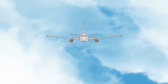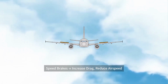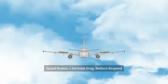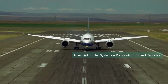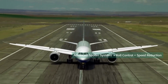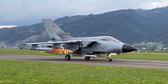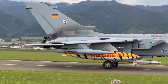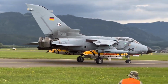When used as speed brakes, spoiler panels on both wings extend upward simultaneously, increasing drag and reducing lift to slow the aircraft during descent. Some aircraft employ advanced spoiler systems, where the spoiler panel on the side of the rising aileron deflects more than the opposite side, combining lateral control with speed reduction. In specialized designs, spoilers or air brakes can also be mounted on the fuselage or near the tail, as seen on aircraft like the Panavia Tornado.